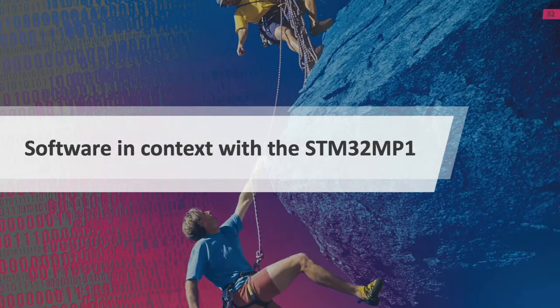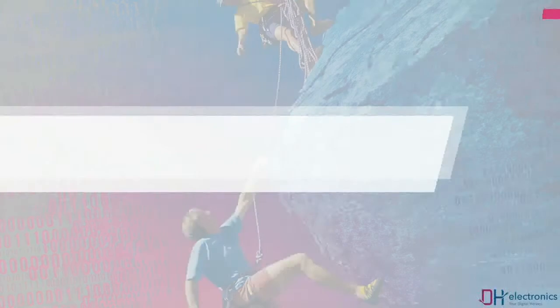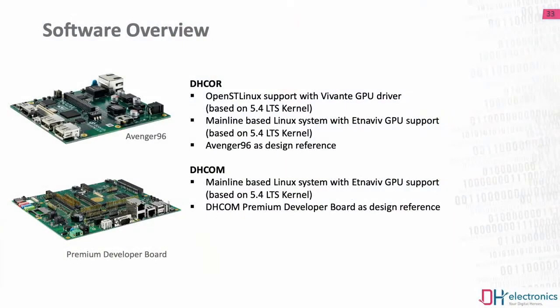So now let's come to the software part of our webinar. On this slide you find an overview about the reference designs where the board support packages are based on. For the DH Core STM32MP1 we have our Avenger96 board. For this, we offer 2 Linux versions, one based on OpenST Linux and a second mainline-based version. It is very important to know that we support the GPU with both available versions.